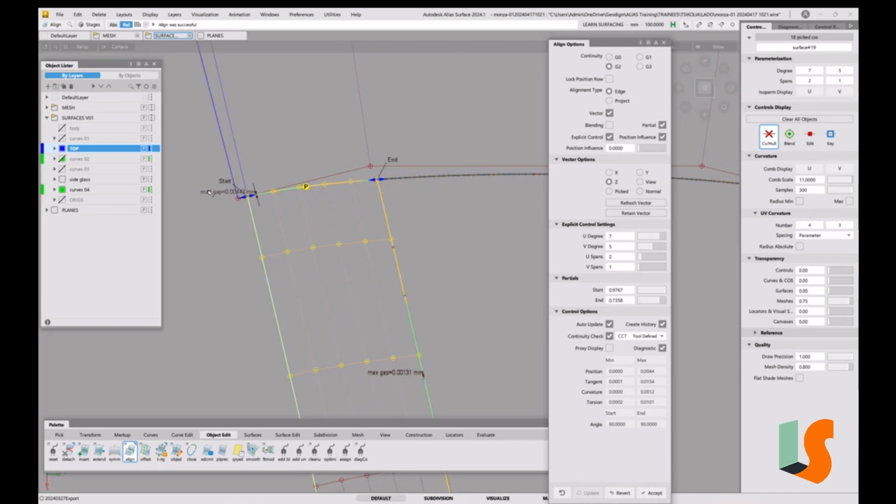We're actually very close now, 0.004 in position, 0.001 in here. Inevitably, it's going to pull this away because we're affecting this hole and this hole. If it's only a small amount, you can sometimes just do a little tweak on position influence, I'm hoping, and get it down to 0.001 without affecting the CVs too much. Or maybe we need to move the CVs.